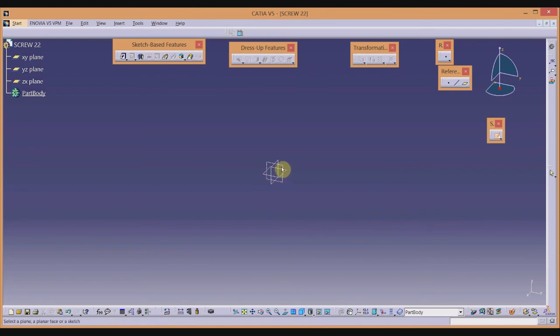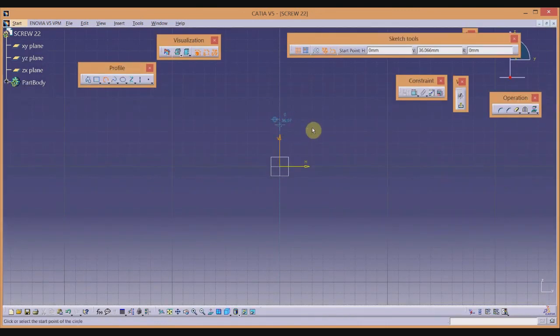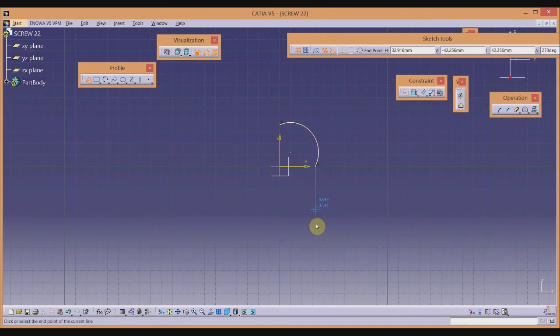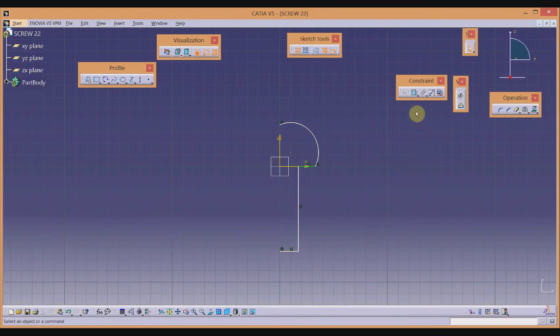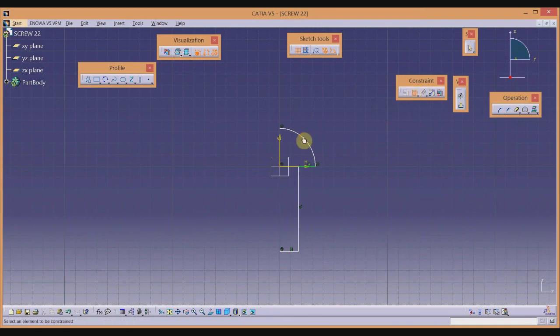Sketch plane, vertical sketch plane. Let us first of all draw the profile of the revolving feature, this one, then the profile tool. I will go in, will come down about the vertical axis. Center of this arc is at the origin, coincide. Radius of this arc is 15.